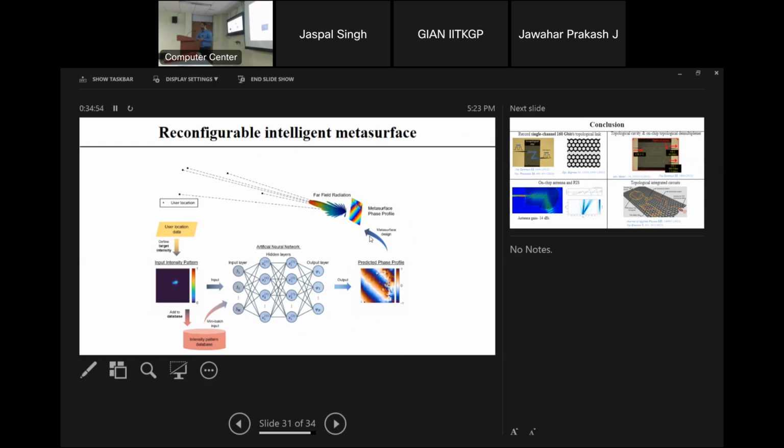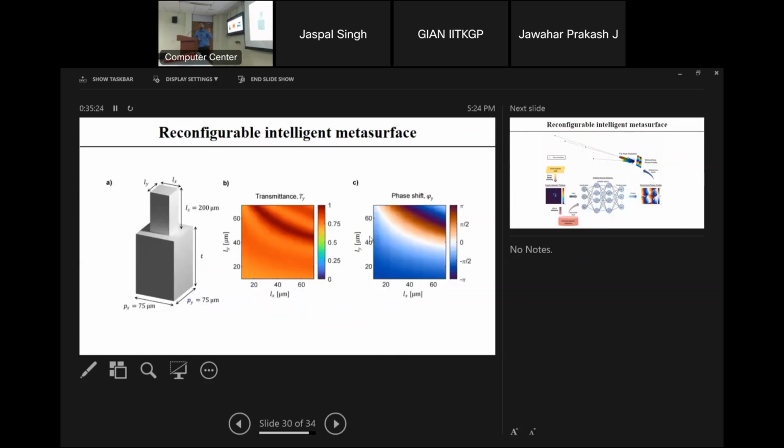You can try using this ferroelectric liquid crystals. Yes, liquid crystal SLMs are very fast. But I think that is very good for optical frequencies. I have to bring that into the terahertz. Yeah, liquid crystal people use it in terahertz. I know, but one of the problems with liquid crystal is it can only provide on and off states, nothing in the intermediate. We need something that covers the full phase gradient.